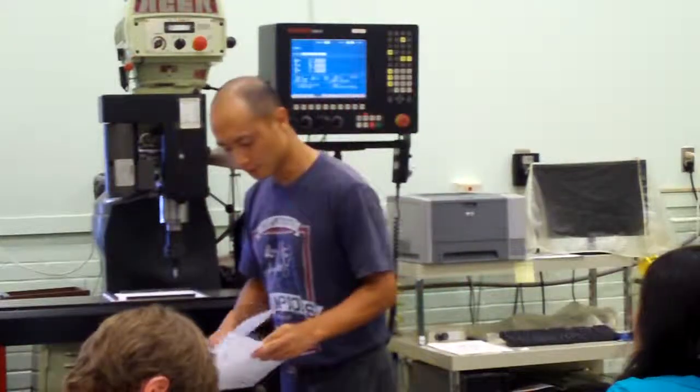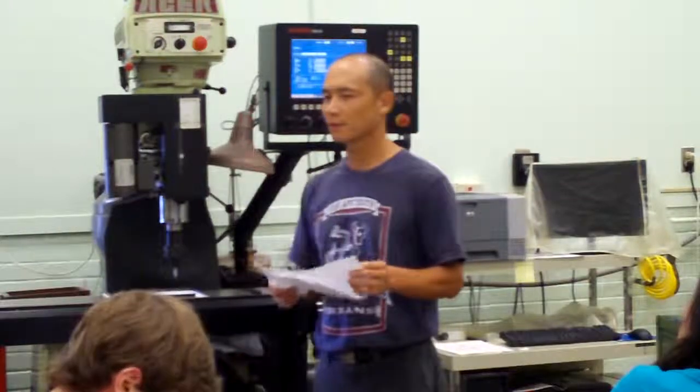Then the next step we are going to drop down the pen, which is N70. We go G1, Z0, the location of Z right on the paper, with a feed of 40. And the feed has been changed to 15 in the circular motion. At the end of the G2, we have F15. Why did we actually change the feed for circular motion?